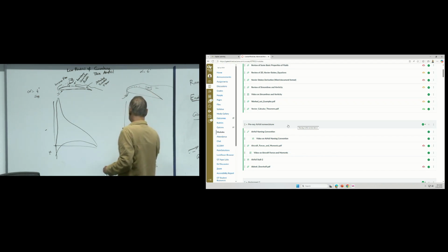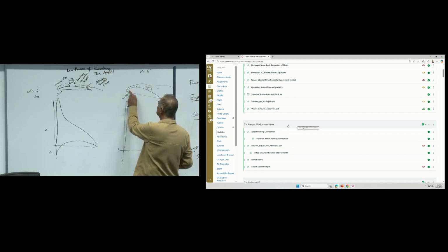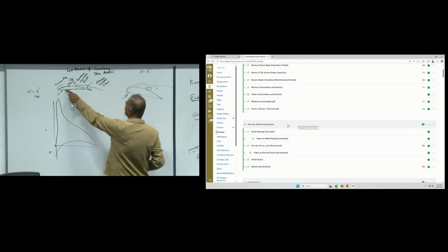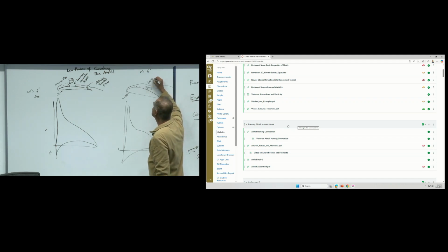So you have a very steep pressure gradient. Then not only does it separate, but the bubble cannot close. It becomes an open separation. So you get some other behavior like this. So you get a leading edge stall.